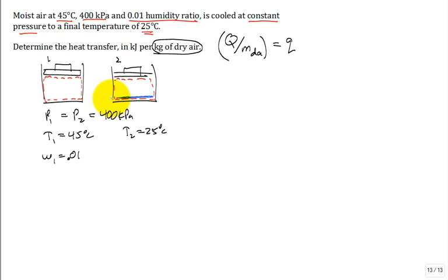Okay. So how am I going to calculate this Q? Well, just write the first law. Do you want to stay with the traditional sign convention, or do you want to abandon it? Either one. You've got to pick one. Either you get on this road or you get on that road. We know it's Q out, but if this is my system and I put Q in, traditional sign convention, I'm going to calculate a negative answer. Do we want to calculate a negative answer? Is that the route we want to go? Yes. Let's stay with it.